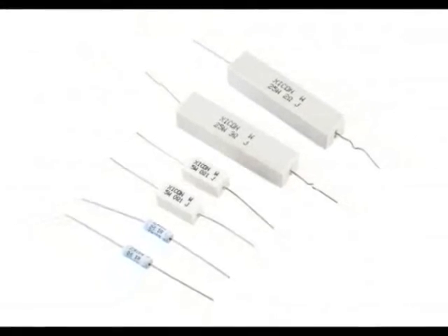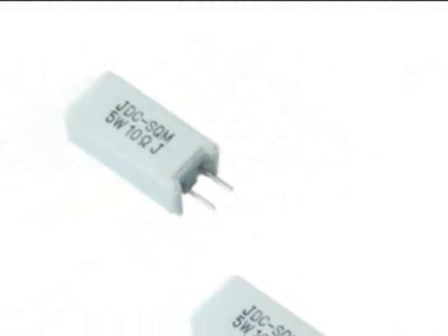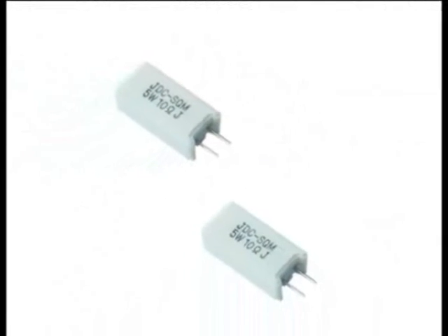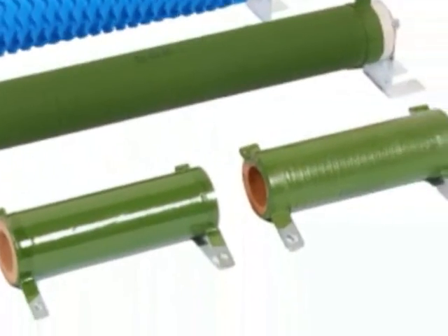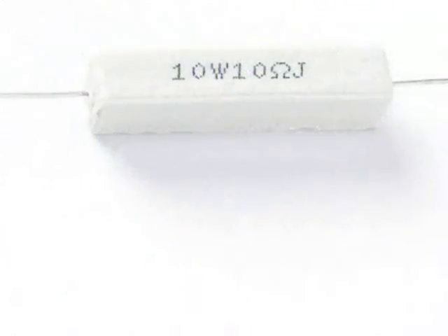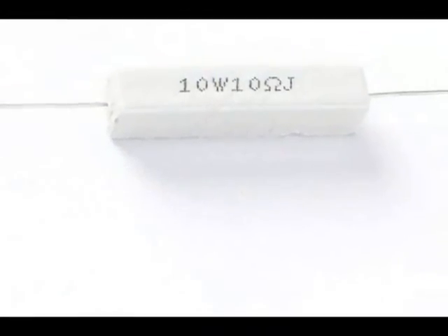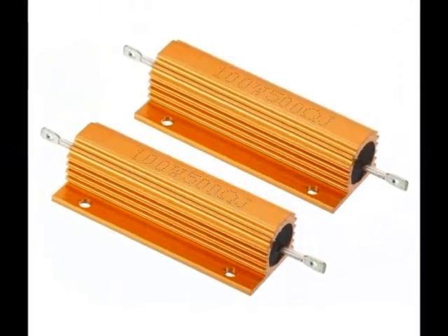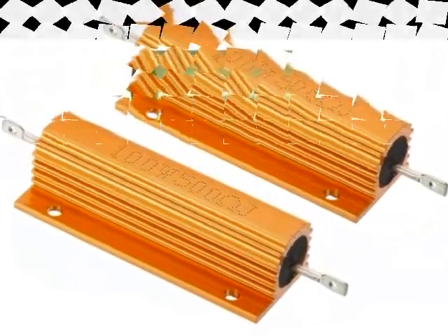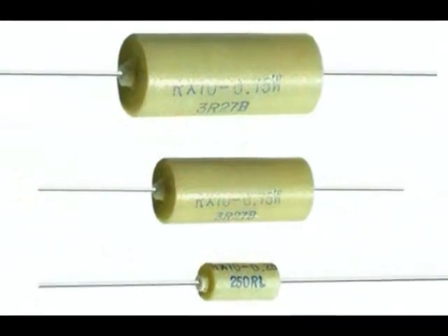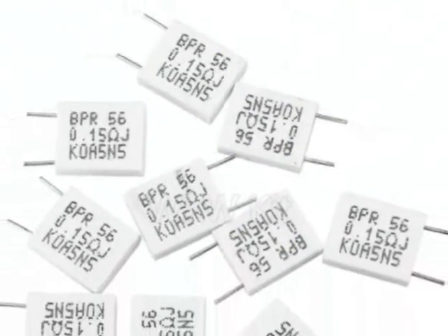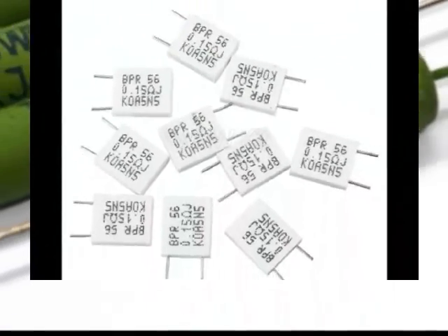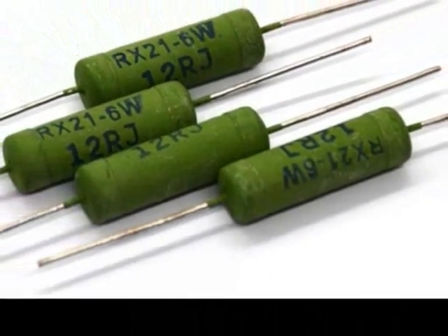Brick resistance is also one of the types of fixed resistance that is placed inside a ceramic cover to withstand high powers and is filled with a special type of insulation under these ceramic covers. These resistors are available in the market from 1 watt to dozens of watts. The important thing about brick resistors is that they may get very hot during operation, and a suitable place for their installation should be considered in the circuit design.